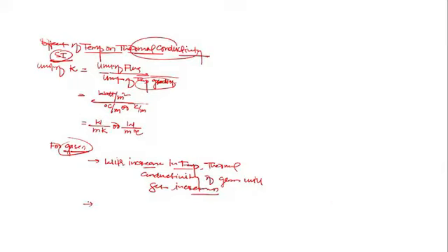Now, second, for solids. In solids there are two cases: one is metals and the other is non-metals. Now listen, in metals, as far as the mechanism of conduction in solids is concerned, I told you the two mechanisms: one is lattice vibration and the other is flow of electrons. So in metals, which one is dominating? 90% of the transfer of energy, or transfer of heat due to conduction, is via flow of free electrons.